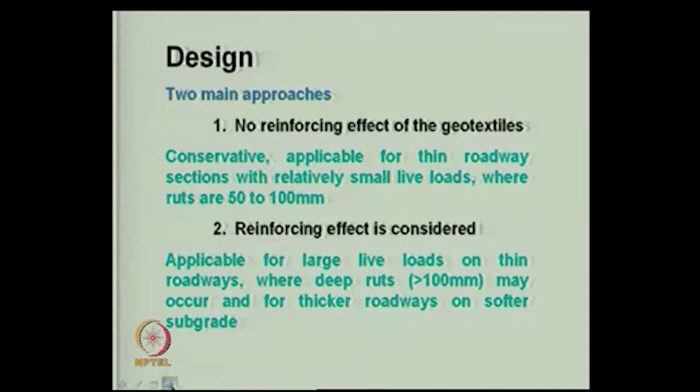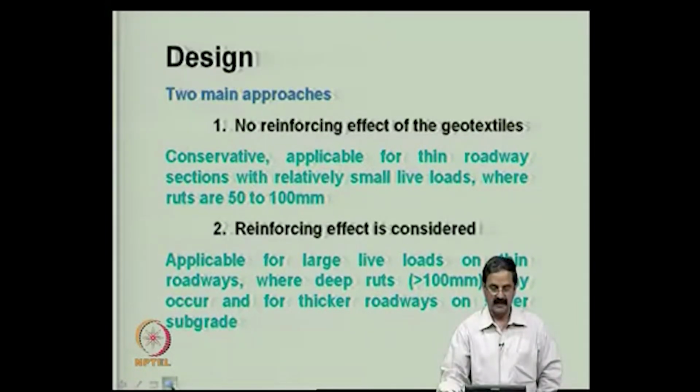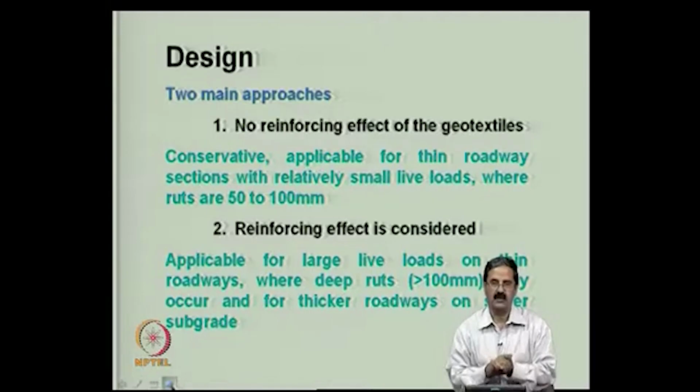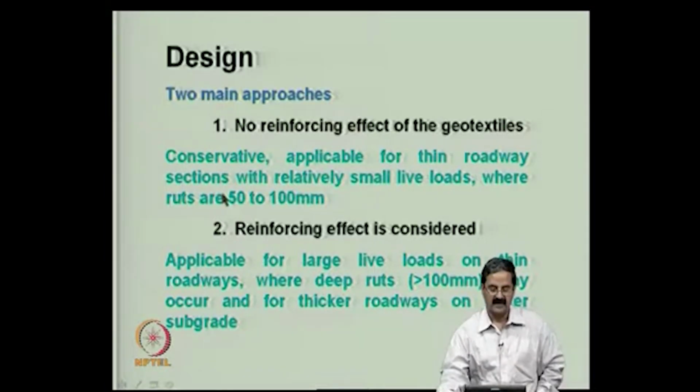So, how do you go about design? As I just mentioned, the provision of a geotextile helps in 2 ways. It acts as a separator and it also acts as a reinforcement layer. So, first, I do not want to consider the reinforcement effect. I will only assume that it works as a separator, right. In that case we will have a design procedure that we will see, and it is quite useful.